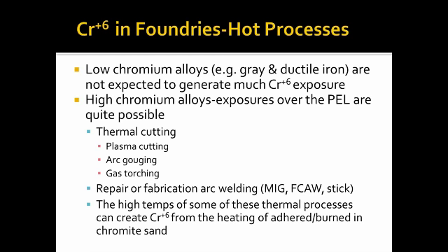And as you note in the little box there to the right, even more concerning is that you can have these processes done on a short-term basis, say 30, 45 minutes, and there's enough hex chrome generated in that time period that the time-weighted average for the employee, even if they have no other exposure for the rest of the shift, can exceed the PEL. So we're talking very high potential exposures with those three red indicated materials.